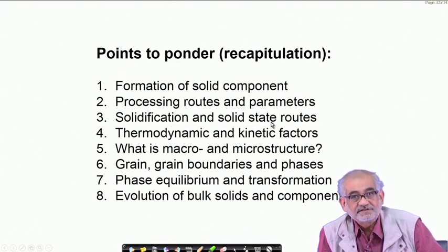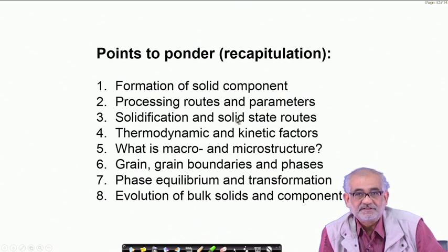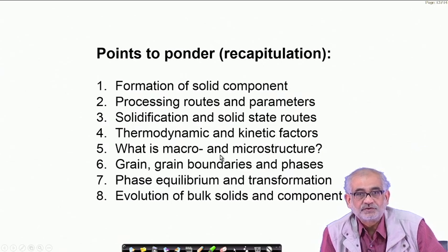We can also form solids from solid itself, and that means that we can allow the solid, by way of either thermal or thermomechanical treatment, to change its phase from one to another, and during such transformation of phases, we can bring in very major changes in the microstructure. And such microstructural changes or evolution will be vastly governed by the thermodynamic and kinetic principles, namely the solubility limits, the diffusion coefficients, and so on.